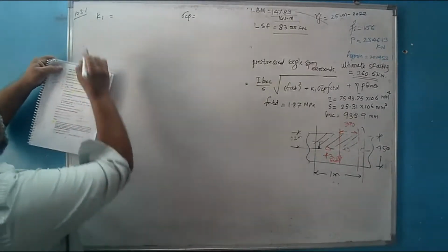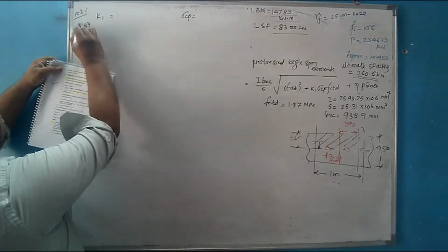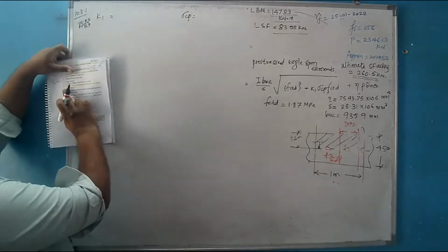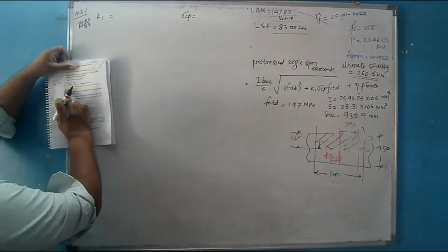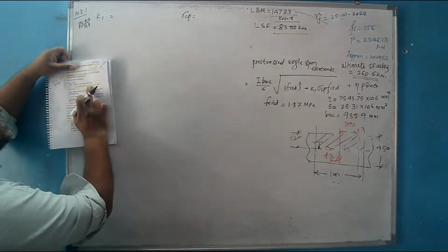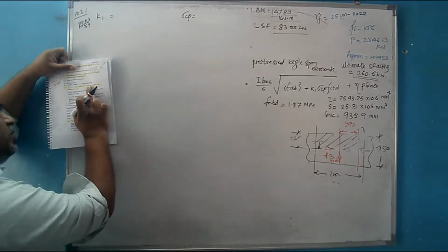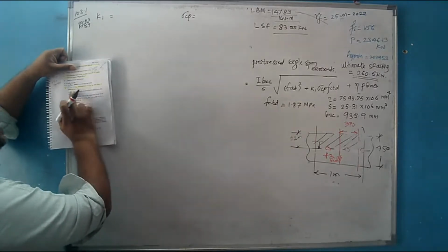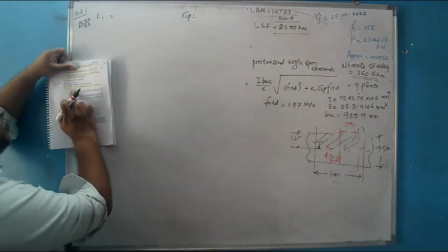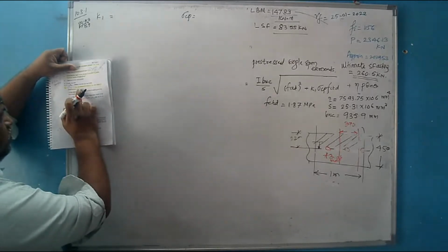It is available on page number 87. This notation is defined. What is K1? LW divided by LPT2 less than or equal to 1 for pre-tension tendons. If it is a pre-tension tendon then we have to see this equation. For other types of pre-stressing, K1 is equal to 1.